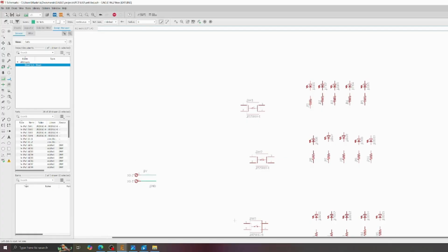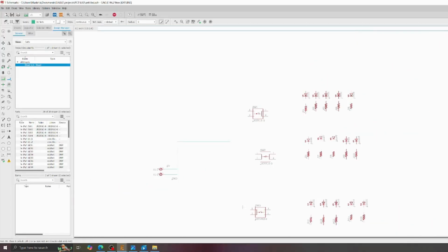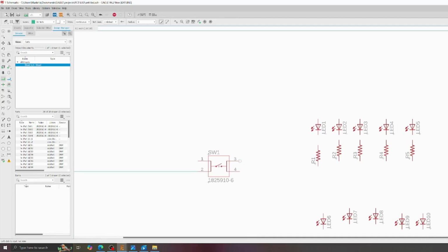So, we're going to grab our net again, and we're going to continue from our 9 volt path, and we're just going to drag it to, again, any of the first 2 components, and then we're going to do it diagonally for the other side. So let's say we choose 2 for here. Now we're going to take 3 and we're going to connect it to the LEDs.